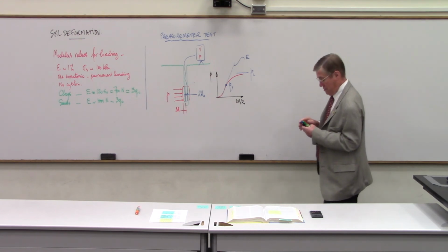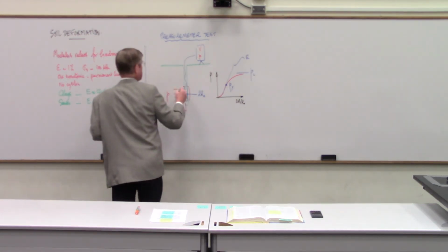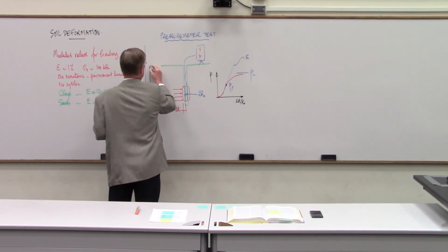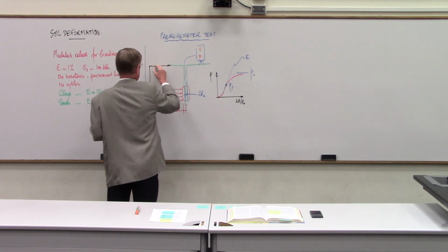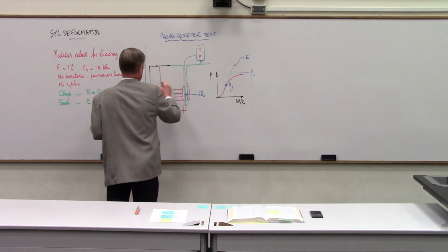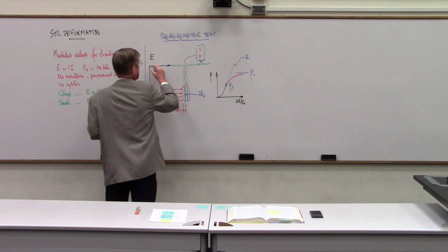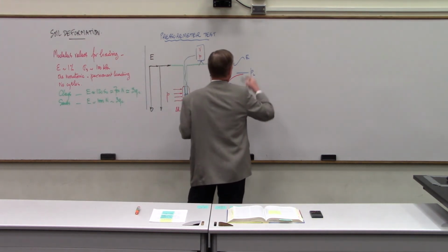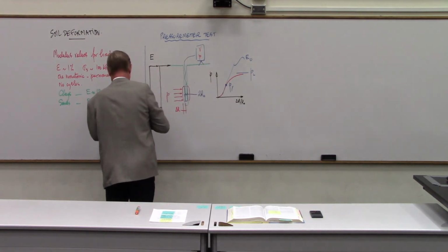So in the end, you obtain a profile, because you don't run just one test, but at a location, you will have a number of parameters. So I'm going to put several here. The two main ones being the modulus, we'll call this E0, first load modulus, so the pressuremeter E0.